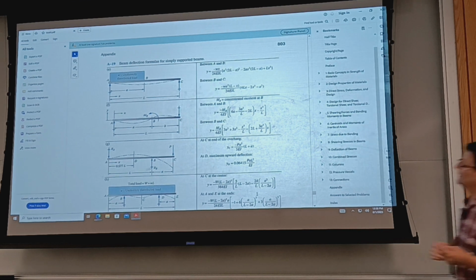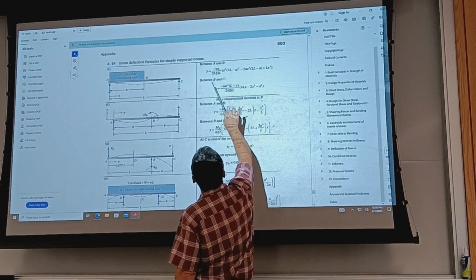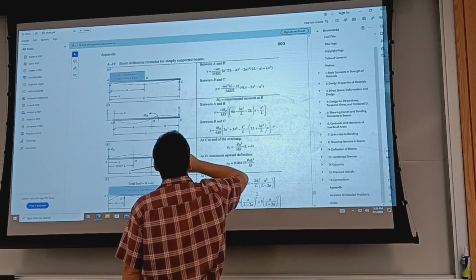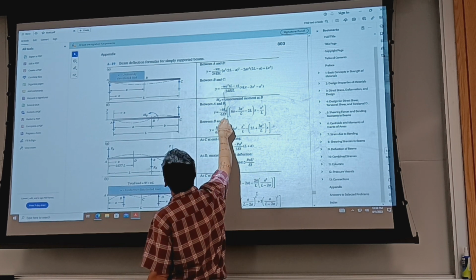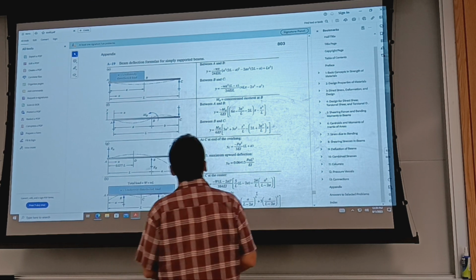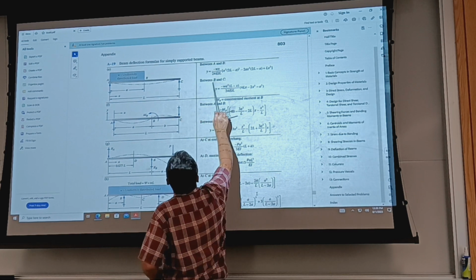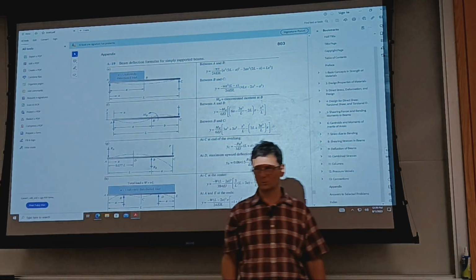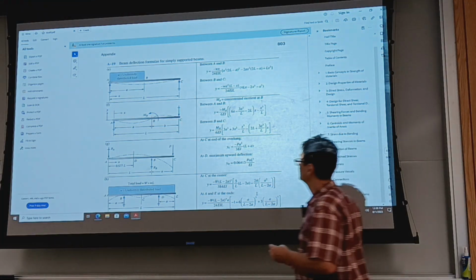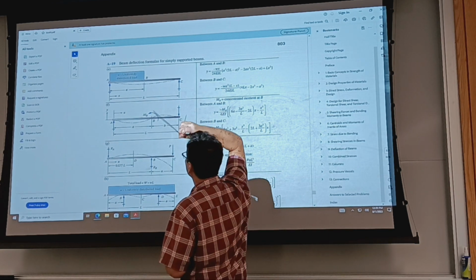All right, in other cases, again, read carefully, look at notations. Here, does it say between A and B, between B and C? It does not tell us where the maximum deflection is. And if it doesn't, then you would have to either look up more detailed information about this kind of loading, or you evaluate the derivative and set it to 0. That gets you, if you calculate the solution to dy over dx equals 0, x at the maximum deflection, then evaluate y at the respective x.